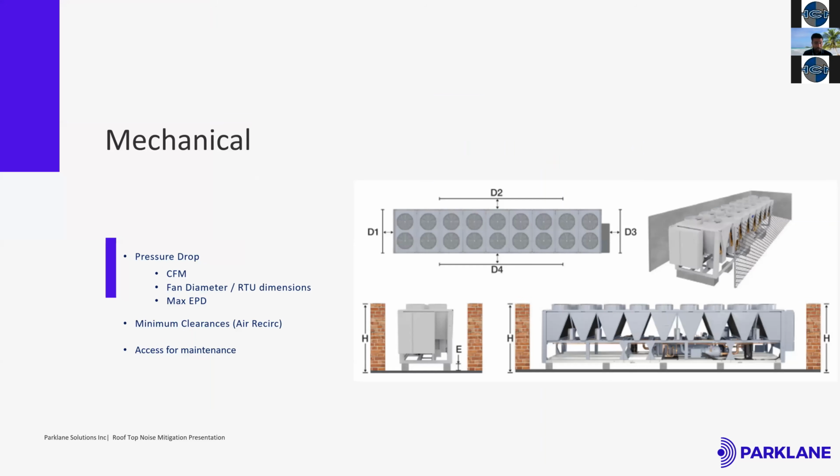For instance, mechanical equipment. In this case, the mechanical consideration is that you have a rooftop equipment. Now, let's say the acoustic consultant has provided an insertion loss to be met, or even a transmission loss to be met. Then one can go about providing a solution by either putting a silencer on the top of the unit or having an acoustic barrier for mitigating the intake noise.